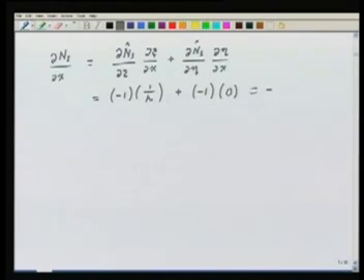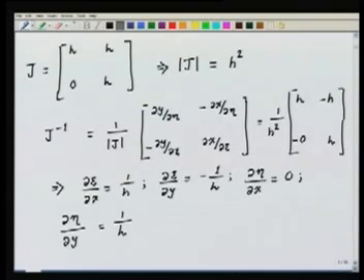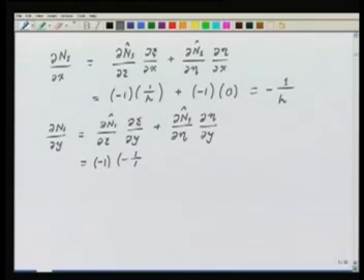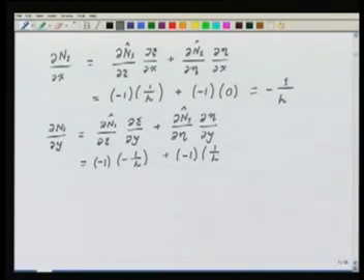So this becomes minus 1 by h. Similarly, del n1 del y would be equal to del n1 hat del psi del y plus del n1 hat del eta del y. Now this will be equal to again minus 1 into, del psi del y is equal to minus 1 by h. So it is going to be minus 1 by h plus, this quantity is minus 1, del eta del y for us is 1 by h, so it's 1 by h. So this becomes plus 1 by h minus 1 by h, which is 0.